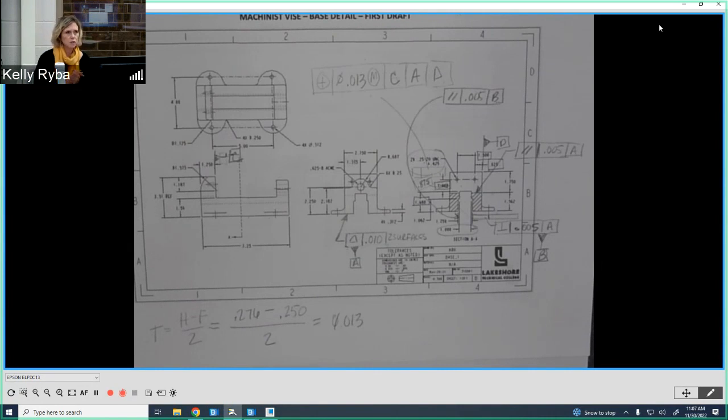And because it's a machinist vice, I don't want to give the interpretation that GD&T is only when we have things that are critical, but we also use it when we need a refinement on what the dimensions offer us, okay? And especially with position, it gives us more freedom for actually opening up the tolerance as opposed to being more restrictive.